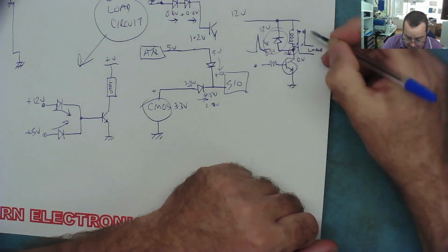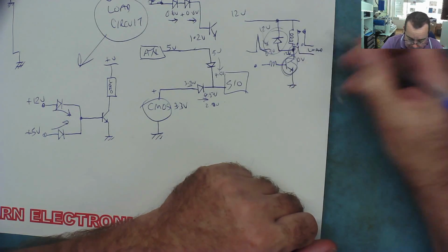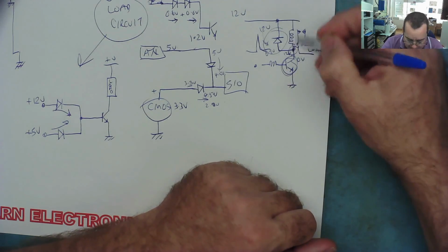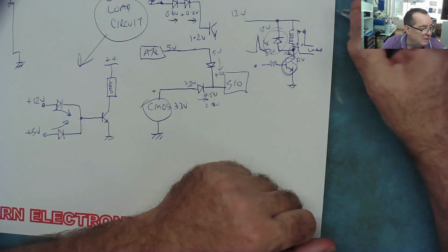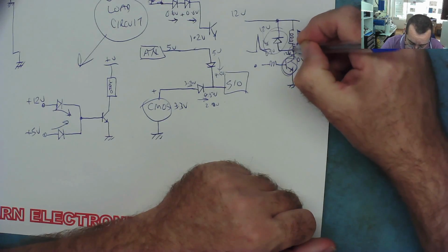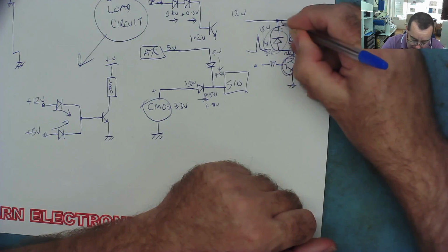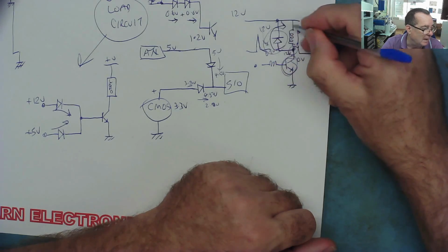So you get a big spike. That spike may well be too much voltage for this transistor to withstand. So in fact, when you switch it off, it blows the transistor because of the spike coming from the coil, the inductor. When you put this diode here, it can't happen, because as soon as you get a spike here, this end goes a higher voltage than this end, and this diode shorts the circuit out through the coil. Shorts the high voltage back into the coil.